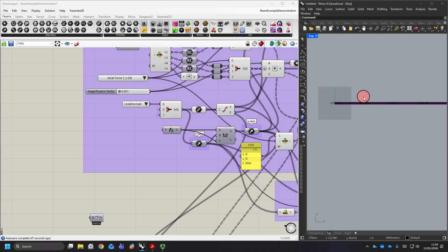Occasionally that will show as minus or positive, just due to very slight rounding errors, but I can also plot my shear force, and you can see the shear force does sort of flash up a few different colors, so it's not perfect. Probably if we did a little bit of rounding here, that would resolve this issue. But what you can see is the actual value that we have is consistent all the way along.